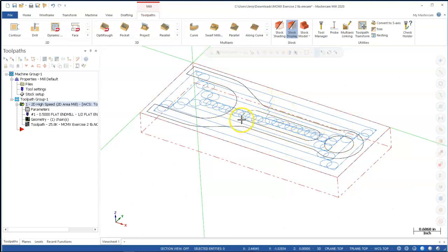Probably don't need that much of a loop, so that would be something I'd go back and adjust. But this is going to be able to have that lead in without coming to a stop, changing direction, coming to a stop, and going. The tool's always going to be in motion, so it gives a little smoother, a little bit better transition as we try to get away from maybe a face mill or loading another tool. All right, so just something to think about.